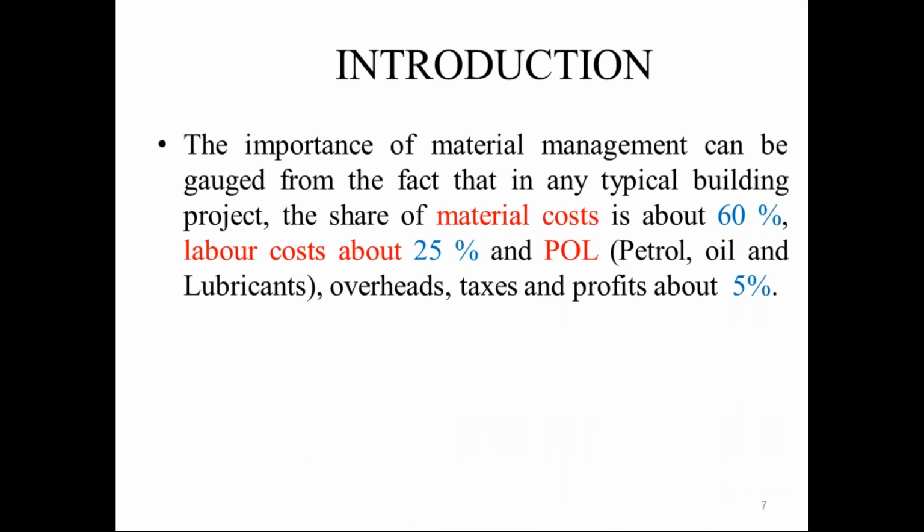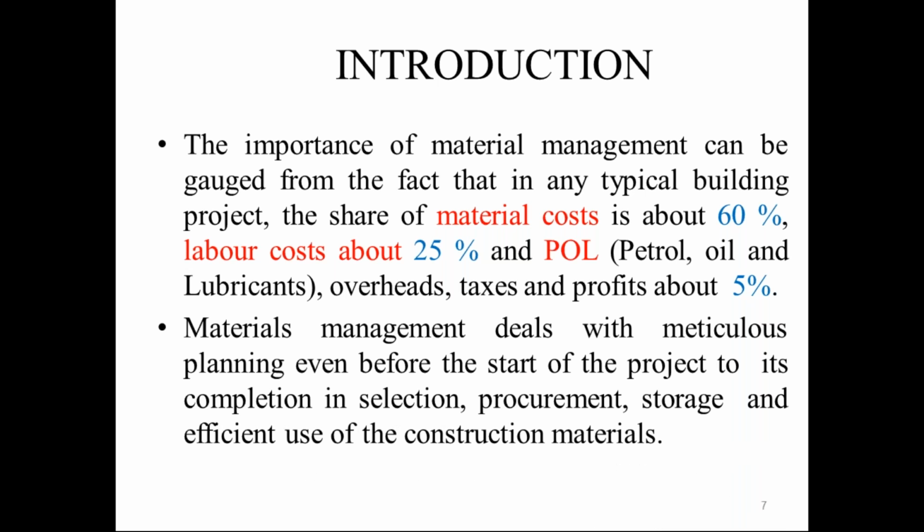Let us start with the importance of materials management. The importance of material management can be gauged from the fact that in any typical building project, the share of material cost is nearly 60%, whereas the other cost, that is labor cost, is nearly 25%, whereas petrol, oil, and lubricants, overheads, taxes, and profits are about 5%. So material management deals with meticulous planning, even before the start of the project to its completion, in selection, procurement, storage, and efficient use of the construction materials.